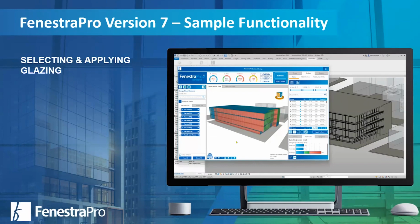And that gives us some advantages, particularly in relation to the performance of the application. As you know, Revit is single threaded. You can do one thing at a time, but by exporting the data into our own environment, we're able to do multiple things at the same time and write that information back into the model. I'm going to show you how we can select and apply different glass types, filtered based on those performance criteria.